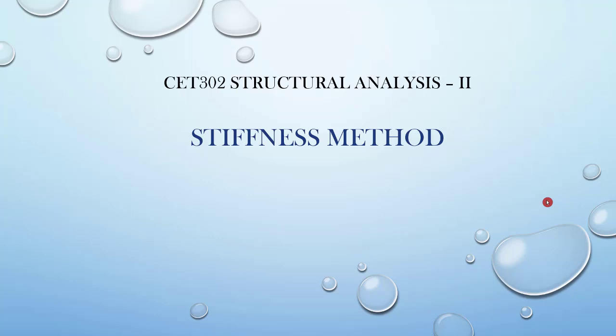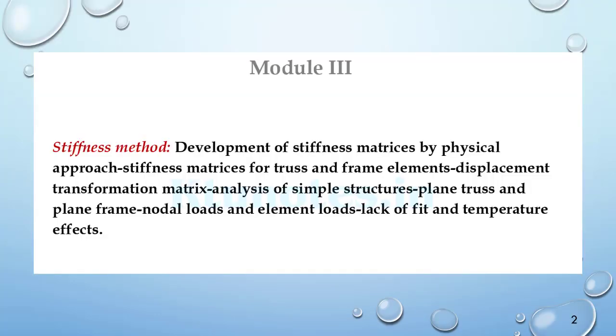So in this video lecture, we will start with the stiffness method. In this module, we will be learning about the stiffness method, the development of the stiffness matrices by the physical approach, stiffness matrices for truss and the frame elements, displacement transformation matrix, analysis of simple structures, plain truss and plain frame, nodal loads and the element loads, lack of fit and temperature effect.